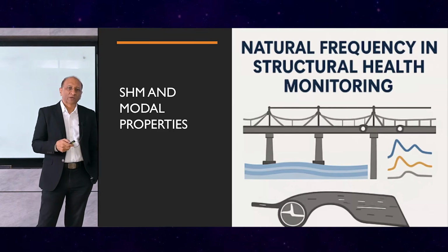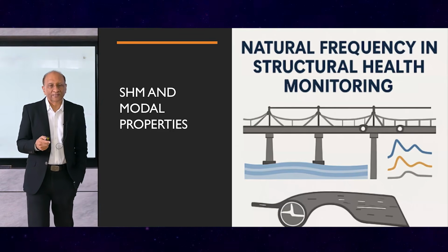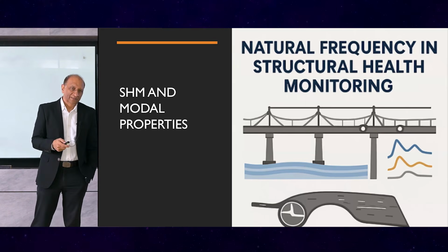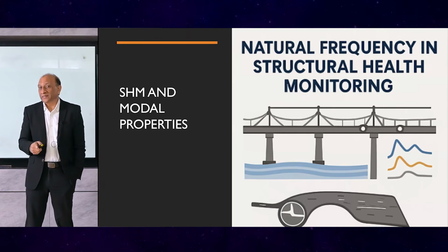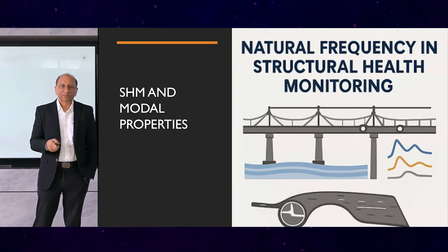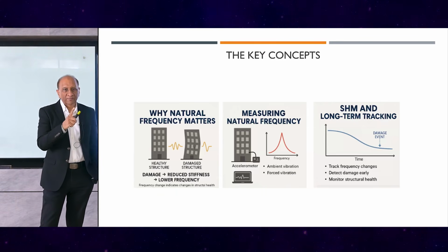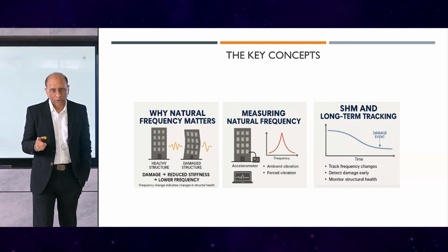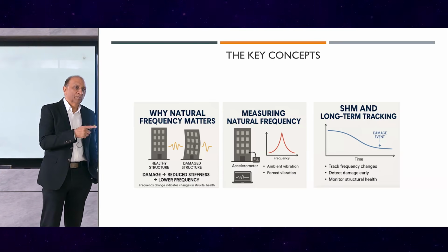And that brings us to structural health monitoring and modal properties. Over the life of the structure, we should monitor the change of the natural period of the building. There are a lot of ways to measure that, because this will not be the same as what we assumed. The damping will change and stiffness will change, so the whole response of the structure can change. So a key concept is that we have to measure the frequency of the structure because it changes over time, and then we need a long-term plan to measure it.